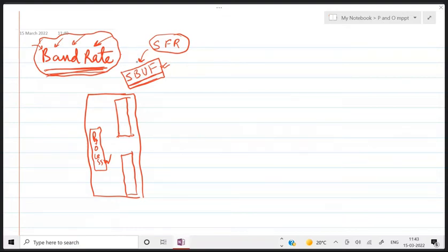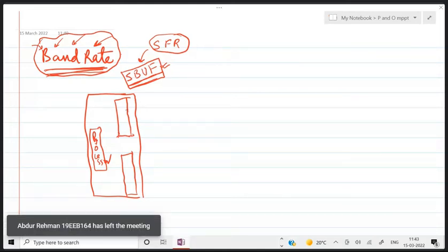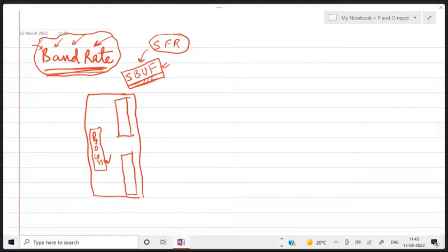Although it looks like the same name might create confusion for the microcontroller to understand whether this SBUF is for transmitting data or for receiving data, it is not the case, because the instruction itself will indicate whether this SBUF is used for transmission or for receiving the data. When I write the instruction, you will know.